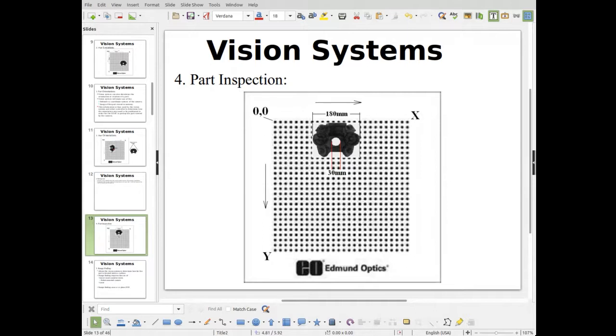And actually, when you get a grid, like Fanuc robots, for instance, when you buy the iRVision for a Fanuc robot, they give you several different grids. They give you a big one that's got big dots on it that are 30 millimeters apart. And then they give you one where the dots are 20 millimeters apart, and then they have a 15 millimeter, and then they have a 10 millimeter one.